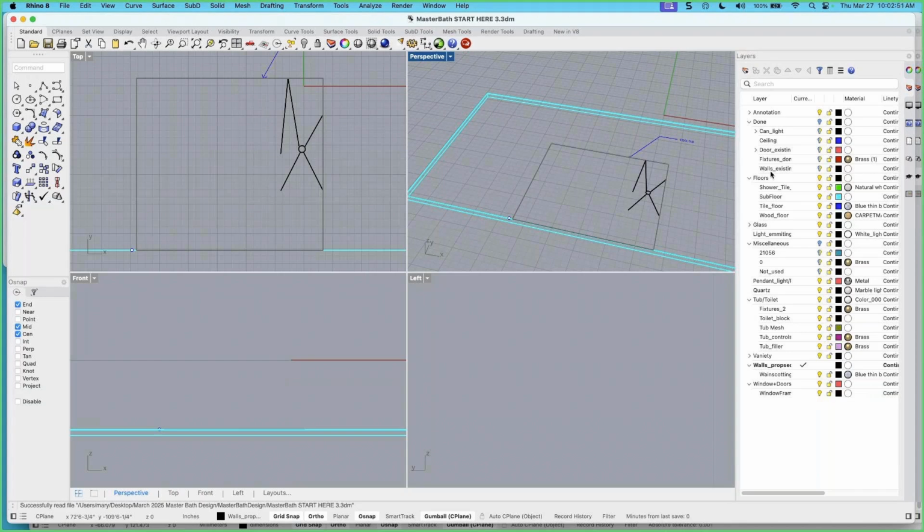So you will be able to do this after you've created a couple projects. You will find that there are likely a common denominator to the layers and the materials that you're using. And if you can save off your own template, or at least begin a model from that model and save as, you'll have a great jump start.